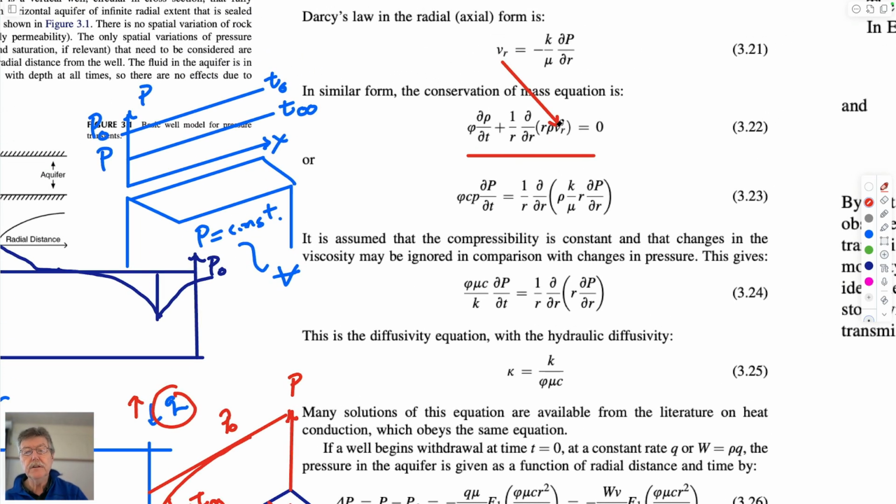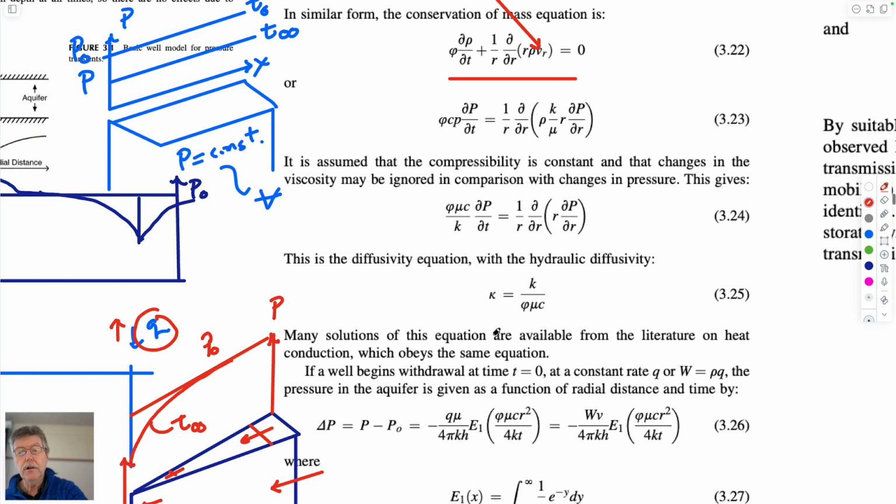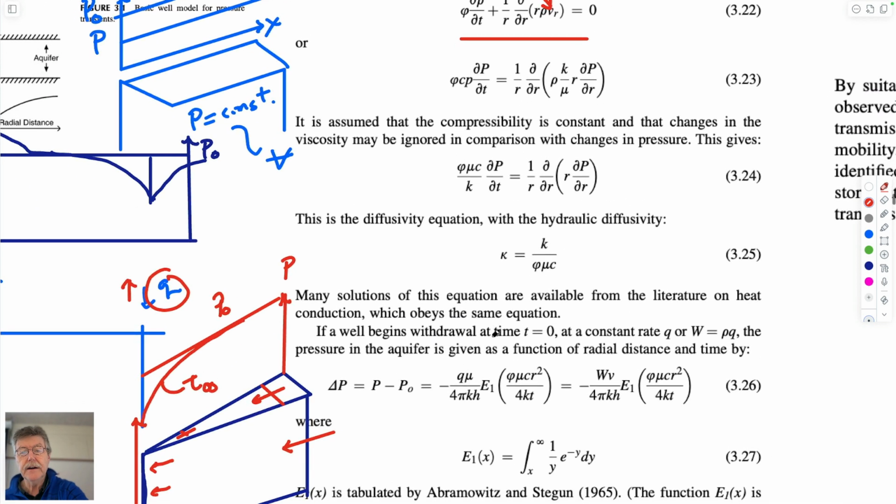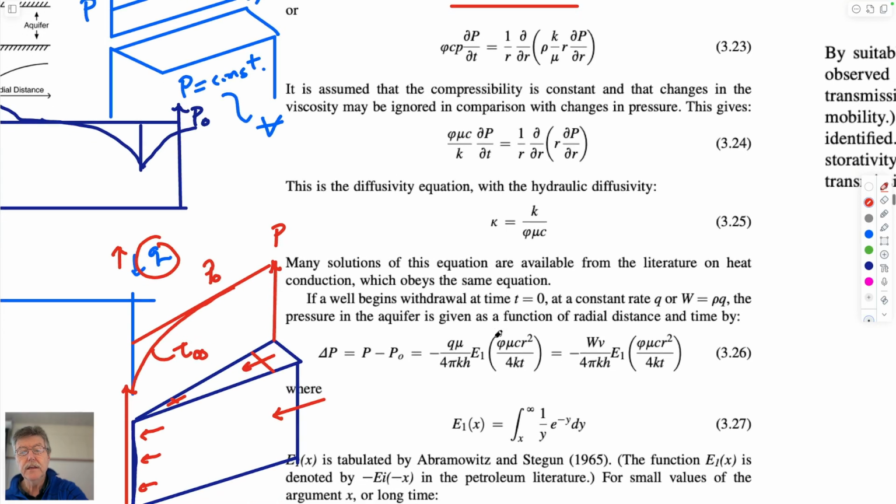So if you substitute into this, you get the continuity equation, you can rearrange it, and you can solve it, and you can define the coefficients that it gets solved for. It defines a hydraulic diffusivity, and I apologize that we switch units around a lot.